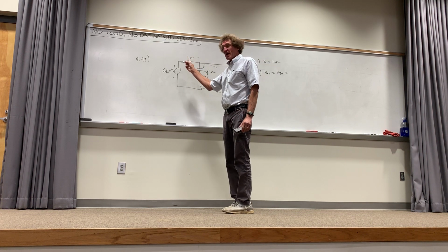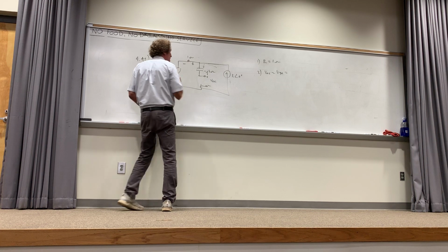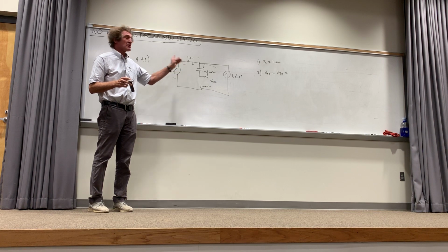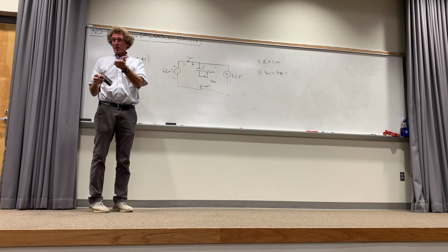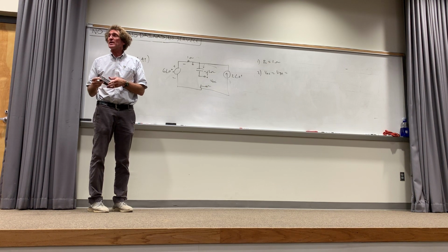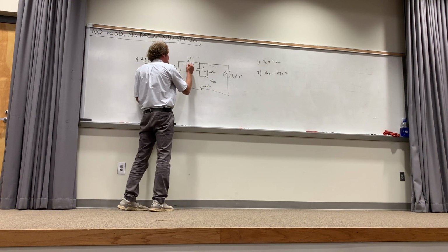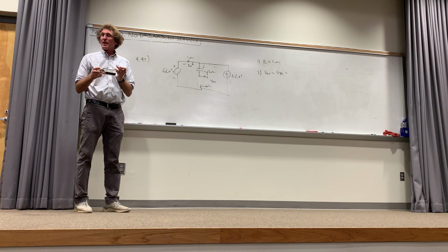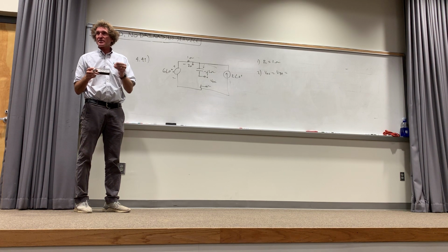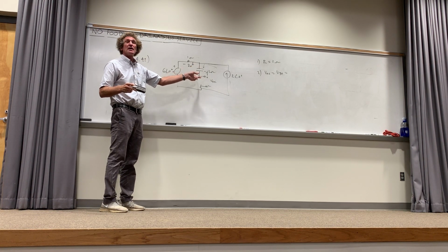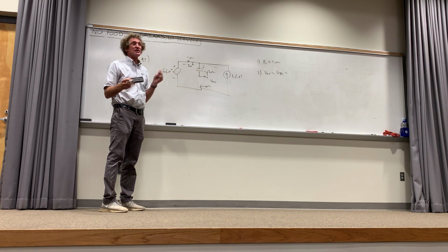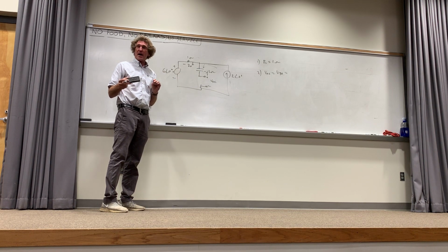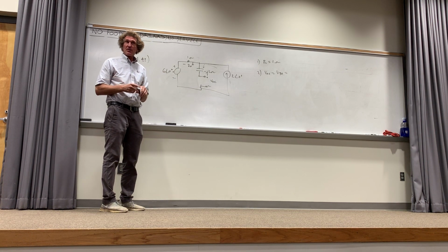If it goes that way, what's the voltage here going to be? You all agree 2 amps is going that way, right? The resistance there is 1 ohm. What is the voltage? It's going to be 2 times 1, or 2 volts. Does everybody see this? I'm not trying to do something here that's going to embarrass somebody. These are just obvious things you have to see. Everybody with me? Now, once I have that, how much current's flowing here? Again, 0. 0 times minus j1 is still 0, is it not? In other words, there's no voltage drop across that capacitor. Does everybody see that?